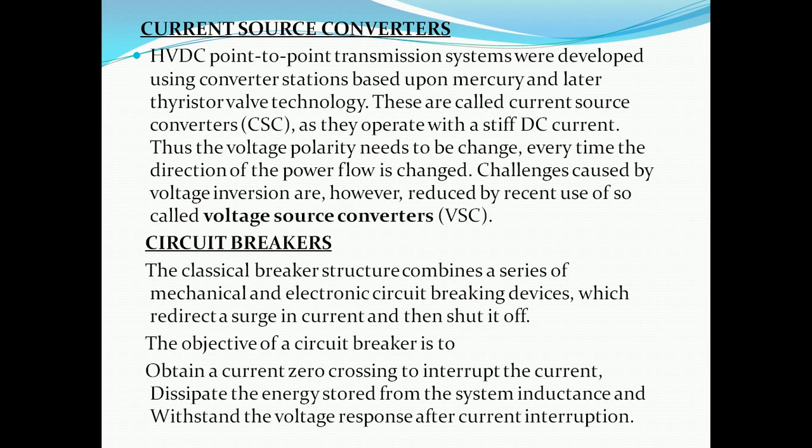These are called current source converters, and they operate with a very stiff DC current. Hence, the voltage polarity needs to change every time the direction of power flow is changed. The voltage inversion that is caused always creates challenges, which can be rectified using a voltage source converter.